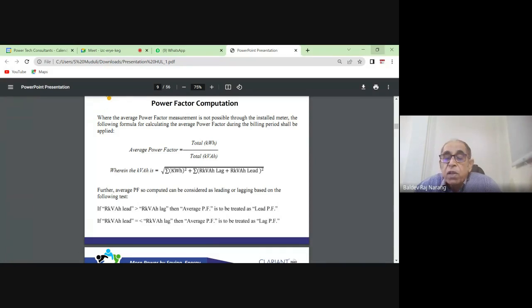So here what is happening is, suppose our power factor is 0.95 lag. So we have, say, about a 5% shortfall in that. And if we are shifting between lag to lead, there is no advantage. Earlier, what was happening is the lead was being ignored. So everybody was maintaining power factor more than unity. They were just going to the leading side. And capacitors people were using as consumables.